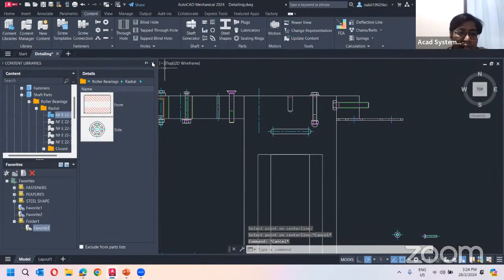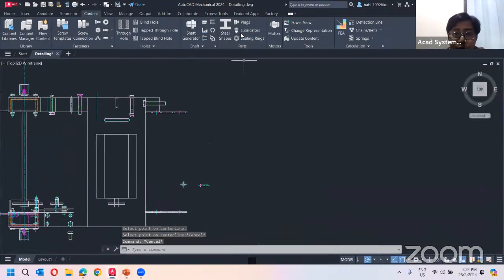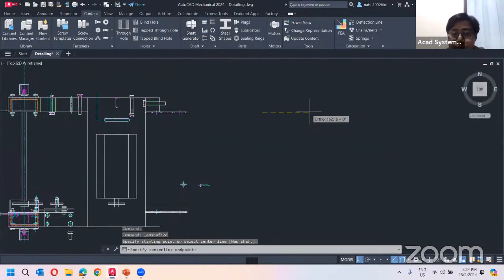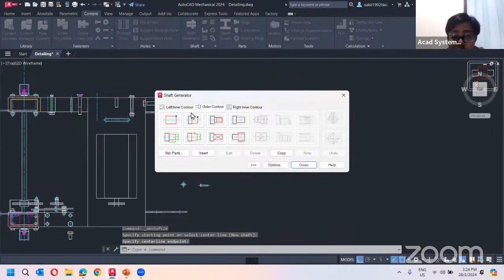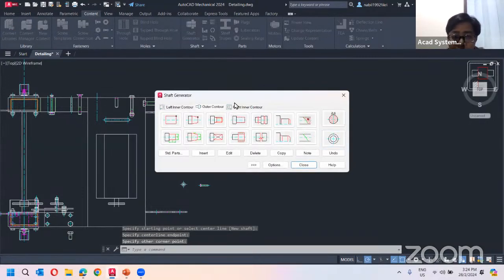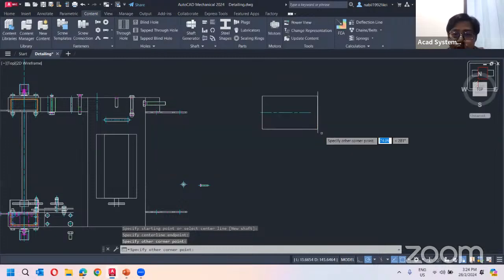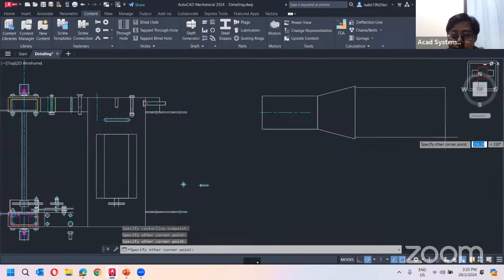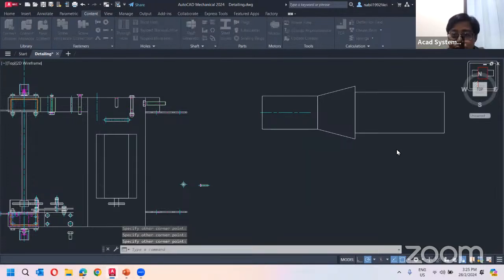So, right, let's take a look at creating the shaft. For the shaft, you can select to generate the shaft from here. You can just click and specify the directions. And then I can specify how I want to create the shaft. So maybe I want to create a cylinder first. So create a cylinder, and then it will have a cone. Continue with the cylinder, slightly smaller.